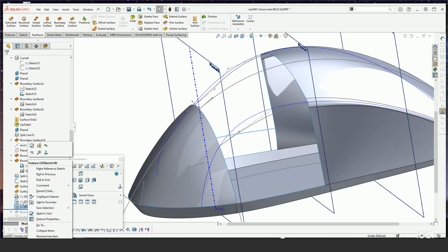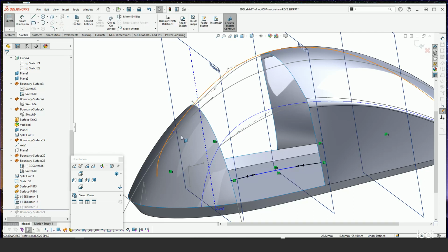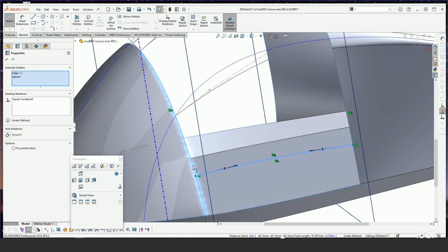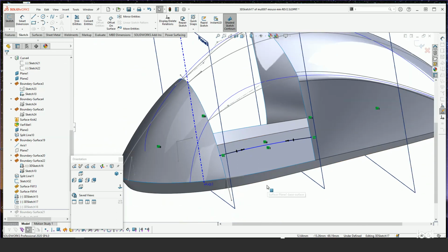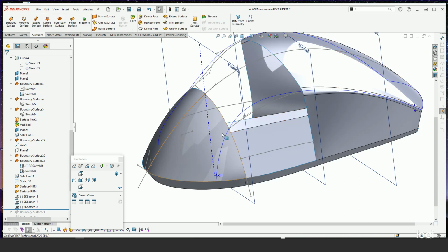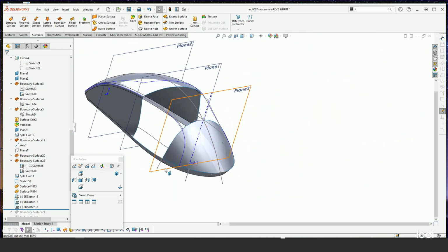So I've then established two more 3D sketch curves using a 2-point spline, but using the same constraint method, clicking on the curve, the surface edge, and then the surface itself, and applying curvature. And by the way, I'm doing curvature on the beginning and end points of all of these because, as I mentioned earlier in my episode, I really want to make sure there's some really good flow and continuity going between these two existing surfaces. So I pretty much have all my curves. Here you can see them